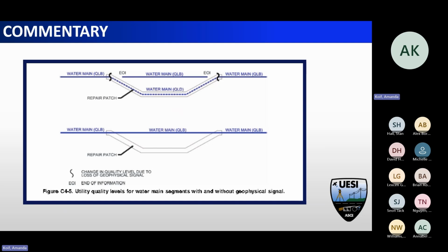What happened when I was doing it, we had a level B line, we dug a hole on it, found it, exactly what we're supposed to do. It was in the grass, unfortunately for me. So we told the geotech, yes, you can drill 5 feet over, you should be clear, because we found the line that we're looking for. And sure enough, they hit that line, because there was a repair on that line that we dug a hole on that was bypassing. So it can happen.